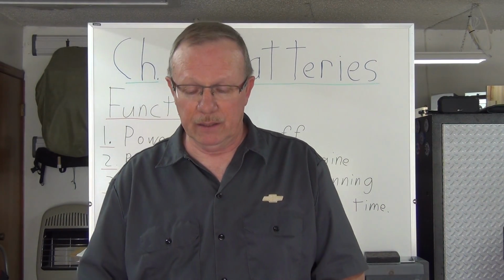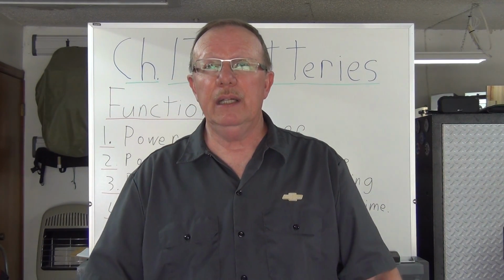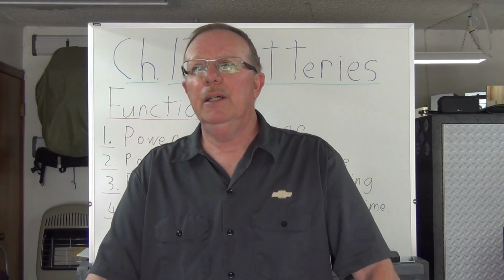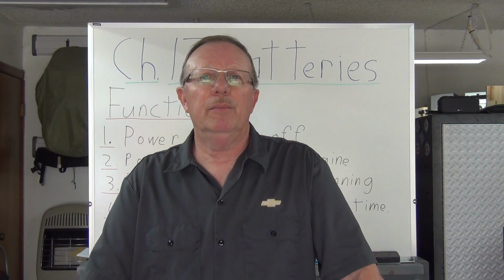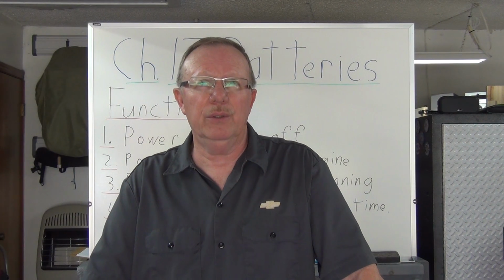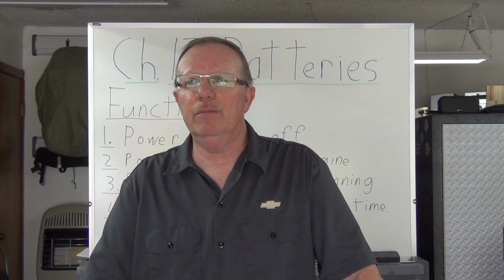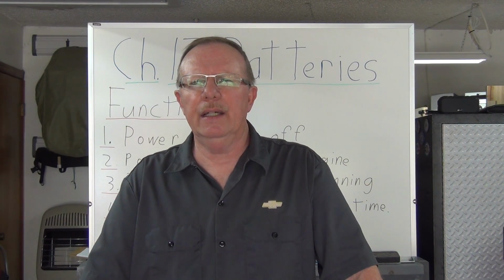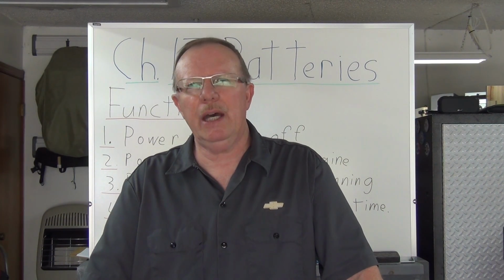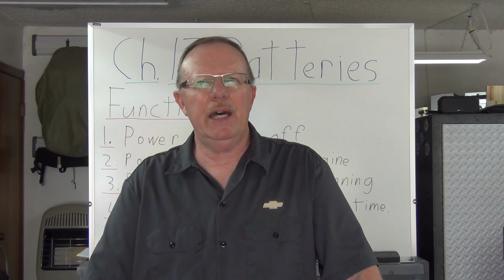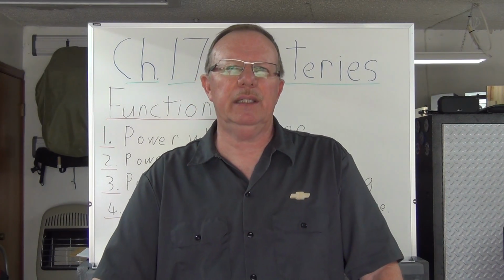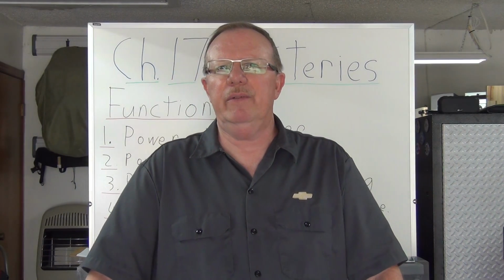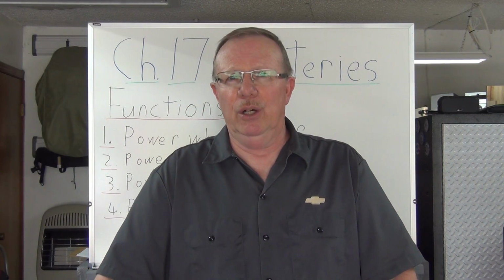There again, I shed a little light on that too. Batteries that sit on the shelf for a long time may need to be charged prior to or when you install it into a vehicle. I've had a particular case in that situation too with a daycare. Daycare had a van that they didn't use very often, and it came in several times complaining about the battery going dead. Right? Put a new battery in it. It'd be gone for 6 months, and then it'd come back and said the battery's dead. They only had 30 miles put on it. Okay, they'd only driven it 30 miles or something like that, you know, in 6 months.